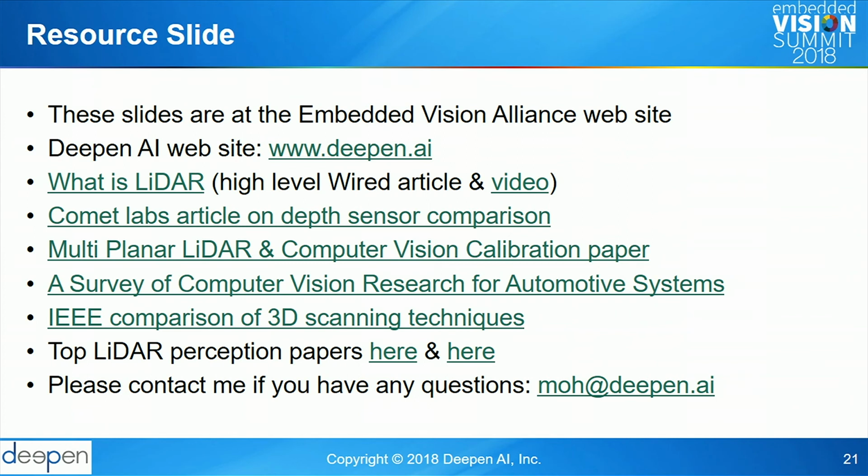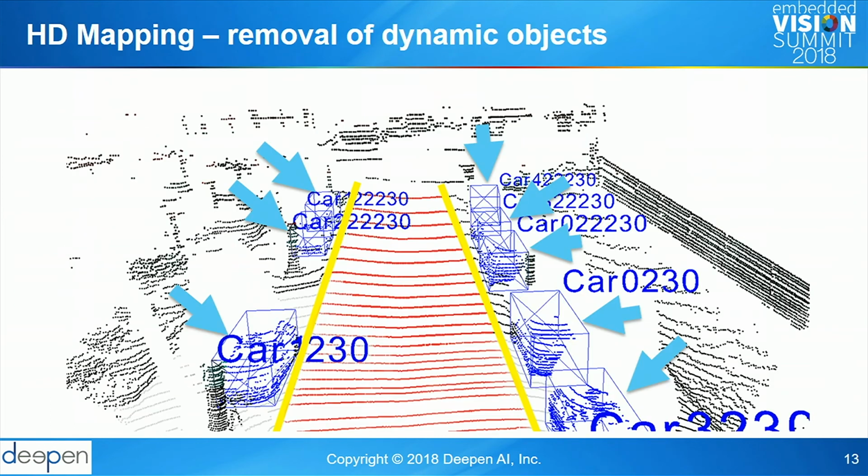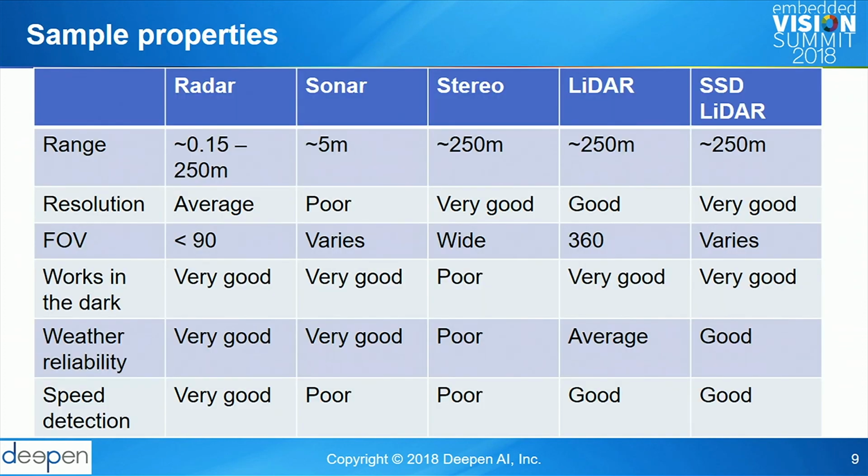In current autonomous vehicles, is the entire burden of object classification on the image system, or is anything done by the LiDAR right now? It depends on the vendor. There are multiple customers we're working with that are using the depth sensor technology, not necessarily just LiDAR, but they're using depth as the major driver for classification. There are 2 or 3 companies that come to mind that say they're camera first or vision only. The thing is, camera, like we saw in that matrix over here, doesn't really do well in bad weather and in the dark. And even if you use an infrared or thermal camera, then that means more parts, more cost, and more processing that you need to add to the vehicle.